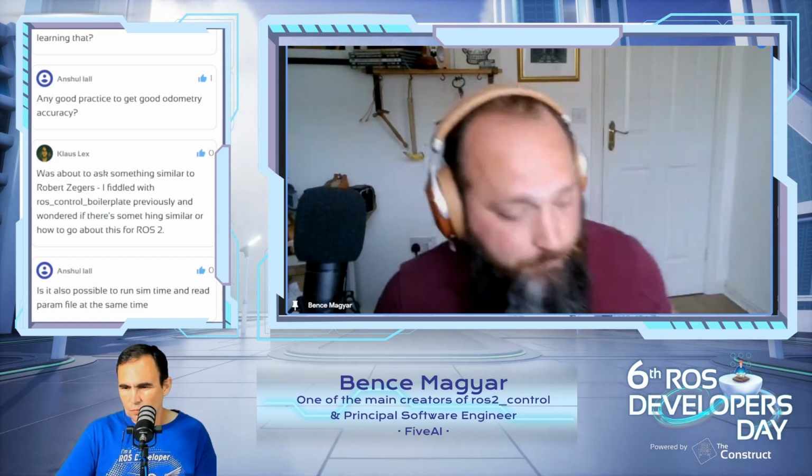And then let me see another question. But by the way, to halfway answer that question, I think if you go back in ROS Developers Day by 2 or 3 years, we had a presentation of going from ROS control to ROS 2 control, drawing some parallels there. But in terms of the ROS 2 control boilerplate, here you need a lot less work to get to a working robot. That's why we wanted to make hardware components plugin based.